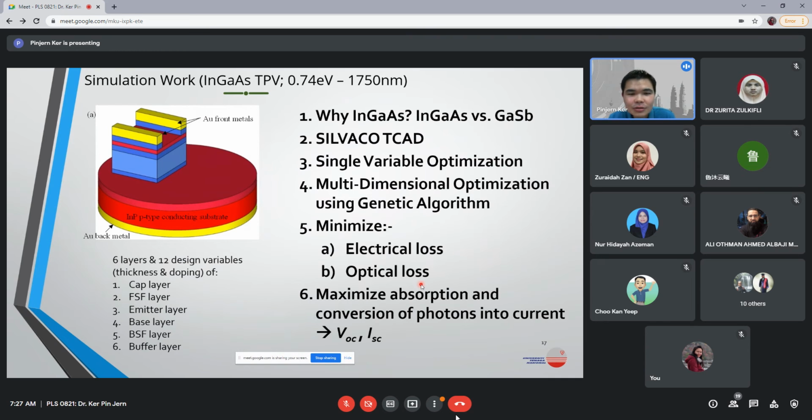Very similar to the solar cell, you are looking at the open circuit voltage, and you are looking at the short circuit current. So VOC, ISC, again, these are very normal and familiar measurements that the solar cell does. It is just that we don't use the AM 1.5 or AM 0 spectrum as in a solar cell, but we use a black body source as our optical source.